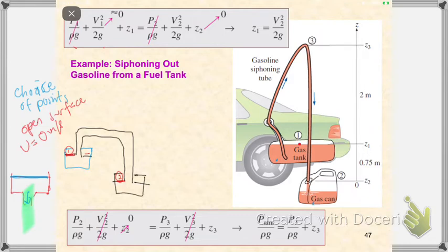Same goes with the second part here. At your outlet, the liquid will flow downward and fill the tank. But at that open surface, you don't see the fluid moving. Only exactly at the outlet of your pipe is the fluid flowing, but on the open surface it's approximately 0. So that's why, from our Bernoulli equation, your V1 can be cancelled out.